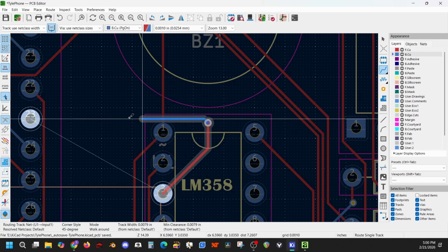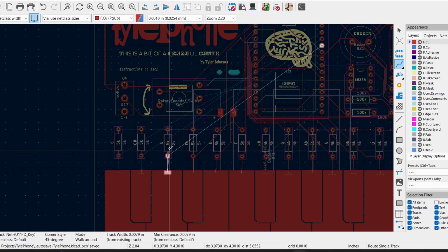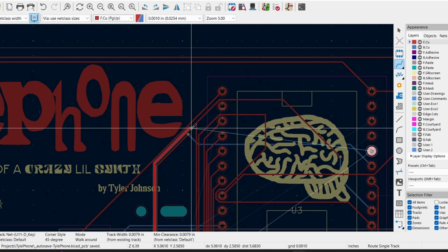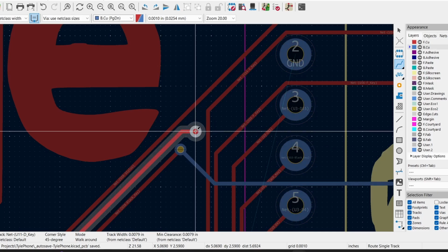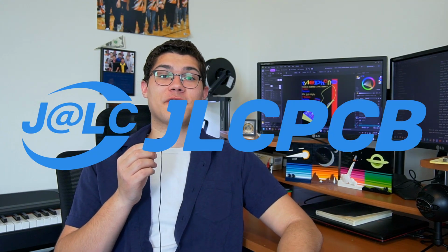One of the coolest things in my opinion is how circuits handle crossing wires. In real life, you can just put wires on top of each other because they're insulated, but with a circuit board, you're gonna cross the streams. So if you need to route a wire and it's completely landlocked, what you can do is punch into the other side of the circuit board, route a wire behind it, and then pop back out. It's called vias, and I thought it was super cool. Once everything was complete, I sent it out to JLC PCB and got 5 of them for 12 bucks.